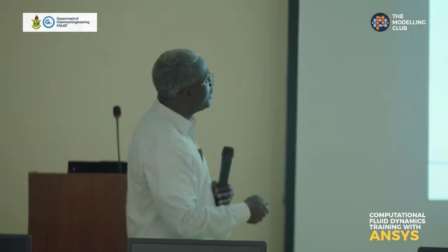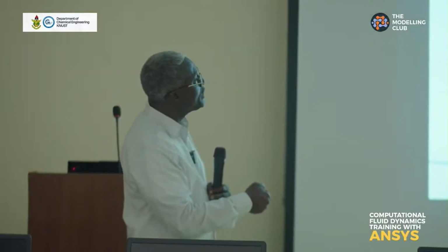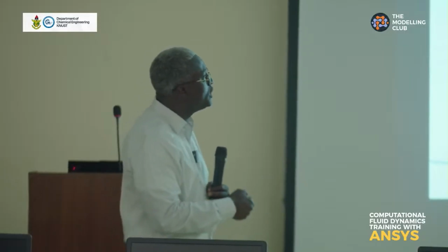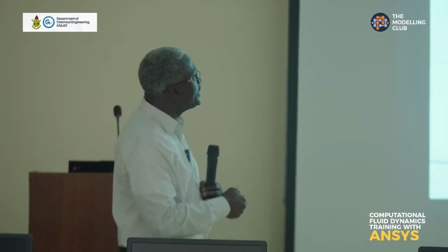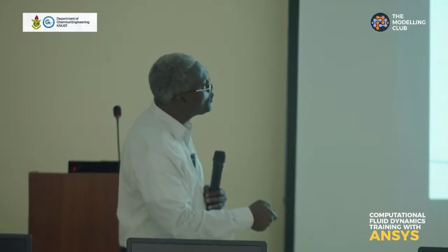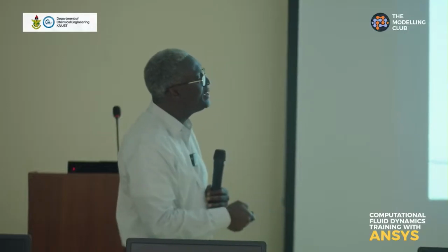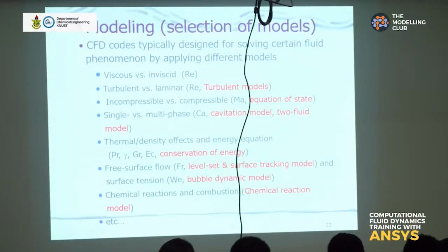And so, yes, we need to determine whether the flow is laminar or turbulent so that we can apply the right turbulence model. We need to determine whether the flow is incompressible or compressible so that, based on the Mach number, we can apply the equation of state or not. We need to know whether we have a single or multi-phase system so that we can apply the correct cavitation model or two-fluid model in the solution of the CFD.